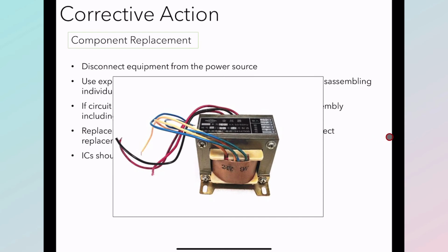So this is a suggestion when the component is being replaced. While removing the previous one, all the leads on the circuit, not on this one but on the circuit, can be numbered, and then numbered on the circuit board also, so that when we are inserting a new component, we connect it the right way.